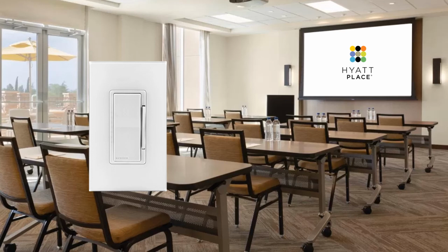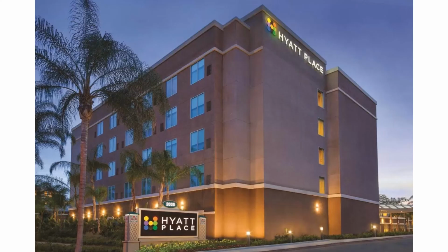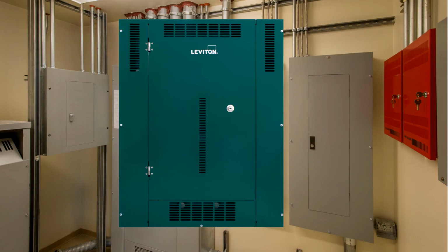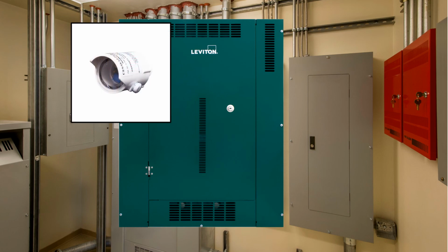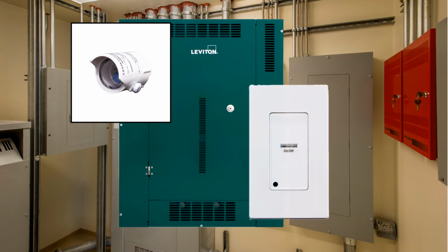Many meeting and gathering rooms are equipped with vacancy sensors. These sensors will turn the lights off automatically 30 minutes after the space becomes vacant. The exterior lighting is automatically controlled by a switching system which is equipped with an astronomical clock. The clock automatically adjusts the lighting to turn on and off based on the sunrise and sunset times each day. These systems are also equipped with a photocell which is set to illuminate the signage on dark, rainy days, welcoming guests to the hotel. A push button has been provided to manually illuminate the lighting for maintenance purposes. No interaction by staff is needed as the system is fully automatic.